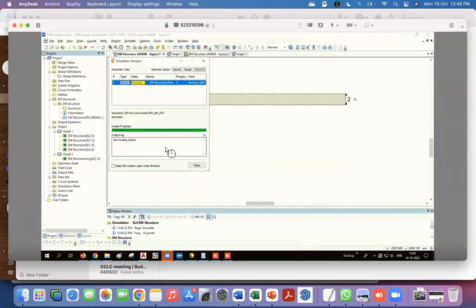Now, usually problems can happen because your mesh is not finely defined. For a very simple structure like a straight transmission line, this is of very little consequence. But if you have structures involving transmission lines of different dimensions which are interfacing, then if you don't tell the simulator that it needs to look very carefully in those transition regions, which means the meshing has to be more precise. It usually does that by itself. It recognizes that things are changing a lot faster. It needs to make, and in fact, we can see that maybe in an example by just looking at the mesh, how it changes near boundaries.